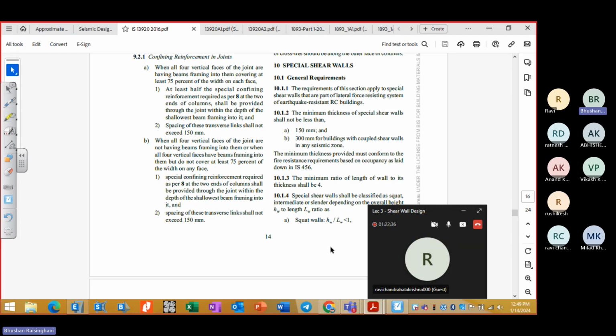Plane elements are dominated by bending and designed for bending action mostly. Here it is dominated by shear. That's why diagonal reinforcement is suggested for coupling beams to take the shear forces, right? Okay, sir. So we will consider it mostly as a deep beam with shell element properties.